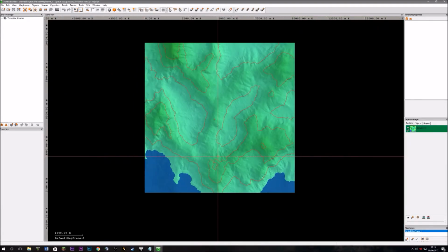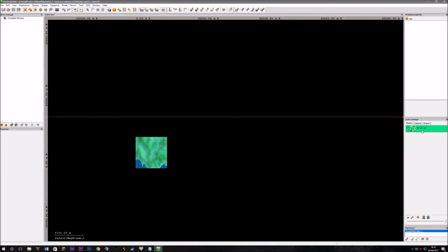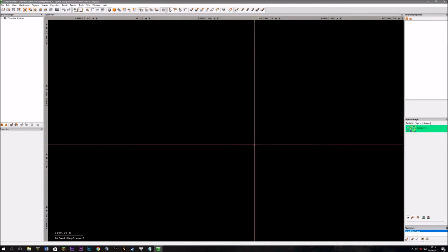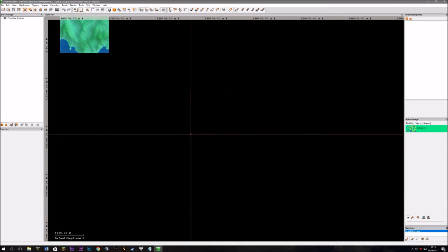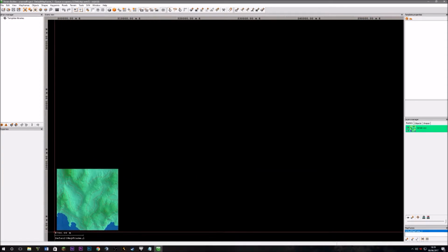So there's our terrain in Terrain Builder. Let's just check its coordinates, and I don't think they're right, to be honest. Yeah, because we couldn't save the map frame. So make sure you go back into here, terrain coordinates and properties, and set easting to 200,000 and northing to 0. So 200,000. And the resolution has to be 1024.0 by 1024.0. So like I said, that would be 10 by 10 kilometers. I think I'm right. Yeah, that's about 10 kilometers. We can see the scale over there.